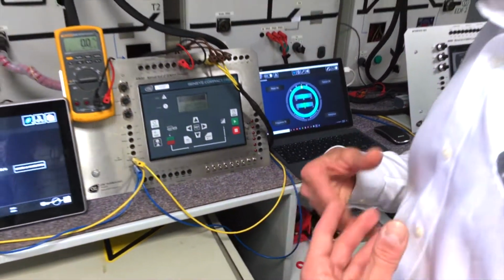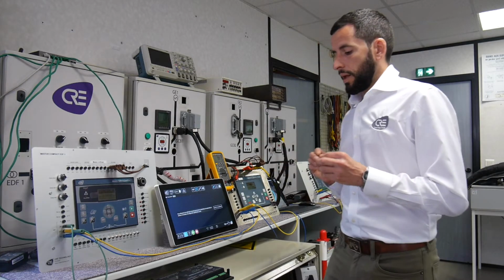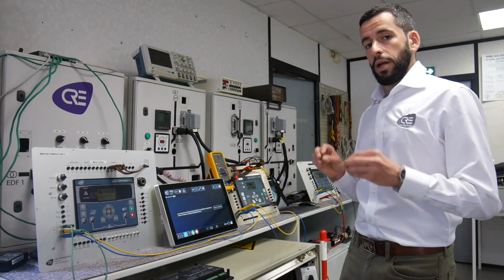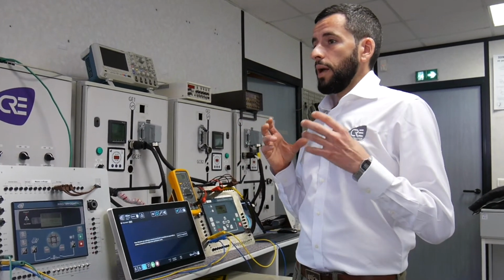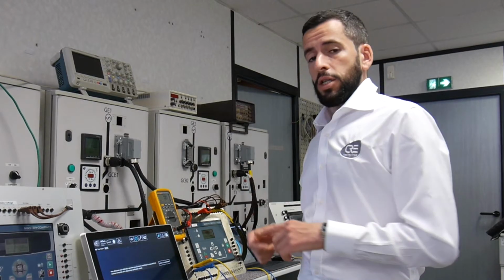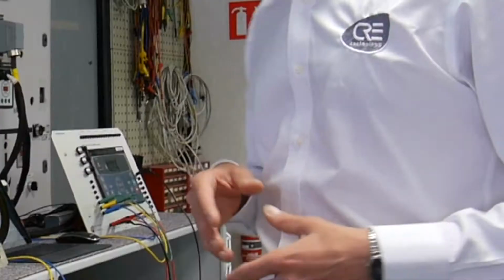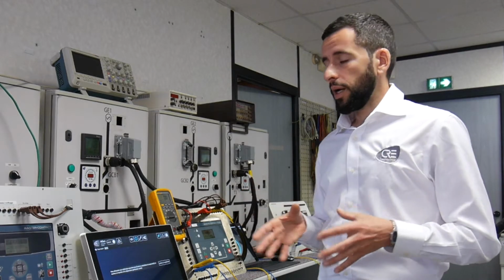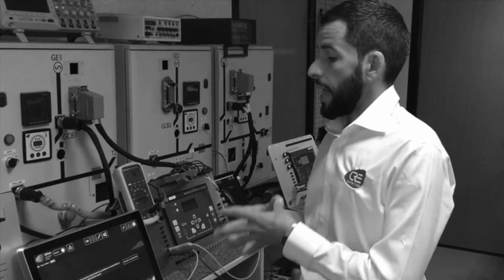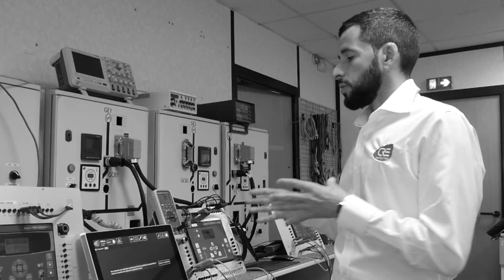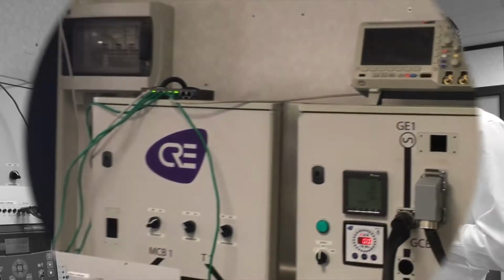EasyCalib will run the sequence that will adjust the signal depending on the AVR expectation and the speed governor expectation. I will adjust the nominal again, and that will make the settings right for synchronization, load sharing, ramping up and down, load transfer, and so on, whatever is your genset paralleling application. The good thing with EasyCalib is that it will tell you every time there is a mistake, and this is what we will see now on the demo.